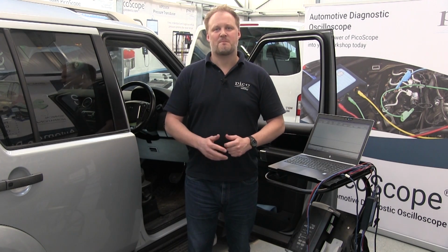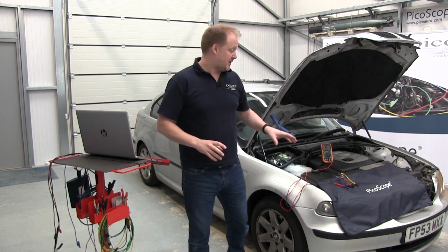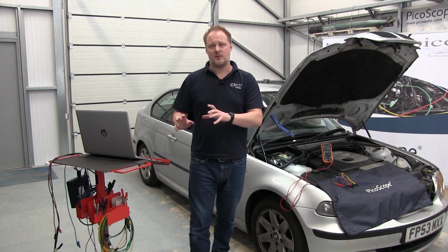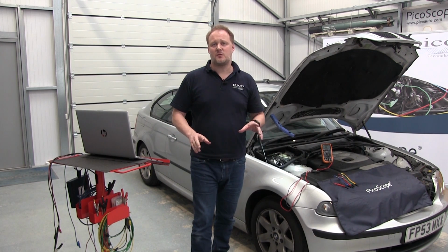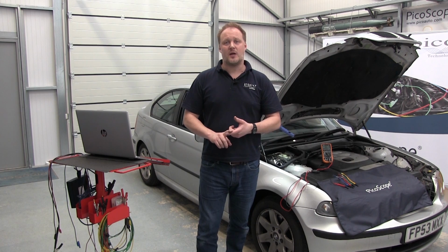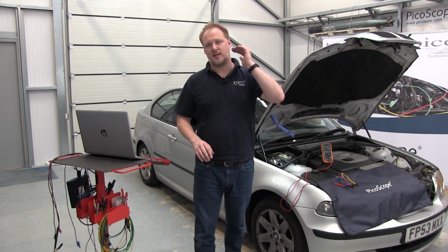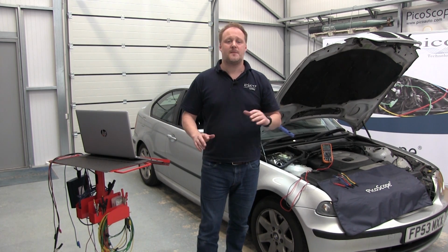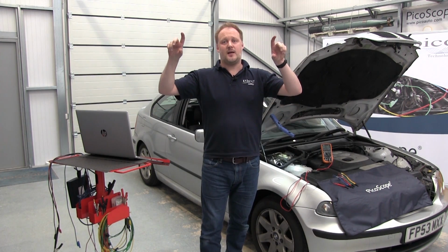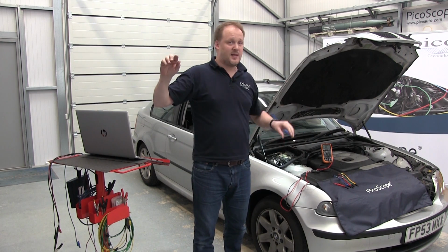control module. Right, before we start to look at any waveforms on the screen to look at our CAN bus health and possible faults, first thing we're going to do is just do a quick CAN bus health check. And to do that, we're going to look at the resistance between the CAN high and the CAN low lines. So if you remember, our CAN bus circuit is effectively a parallel circuit on this high-speed network.